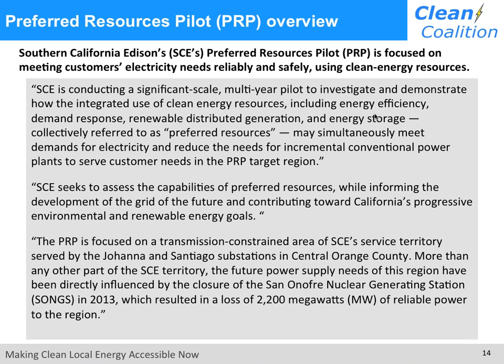They also correspond to the best grid locations typically, so they usually have large loads, so they're served by more robust feeder segments, which means once you go through a power flow model, you realize that that's where you can get more two-way power flow, local generation. So there are fewer issues with the local grid by putting out a lot of solar in those locations.